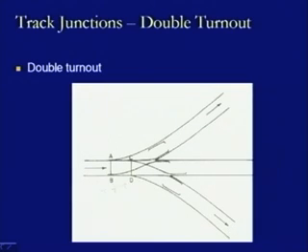So, on the basis of these locations, the components which need to be provided on any double turnout are the two pairs of points and switches, shown as A, B and C, D here. And we have two crossings, one crossing at this location, another crossing at this location. So, here we have one pair of wing rails, here there is another pair of wing rails, and with respect to these wing rails we will be providing the check rails.